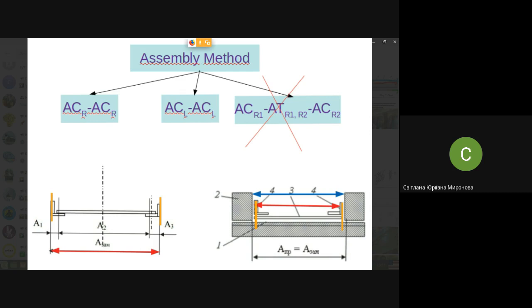First of all, it comes about using lasers, or if necessary, even visualizing bases with a laser beam. It comes about using a coordinate measuring machine and sophisticated equipment. So in this group, together with assembling in a jig, we have so-called jigless assembling, extremely popular in modern manufacturing. But this jigless assembling, of course, has a lot of limitations, because a jig is not only a carrier of bases. A jig also helps us to stiffen the structure.